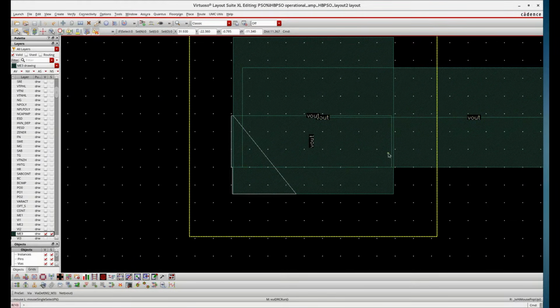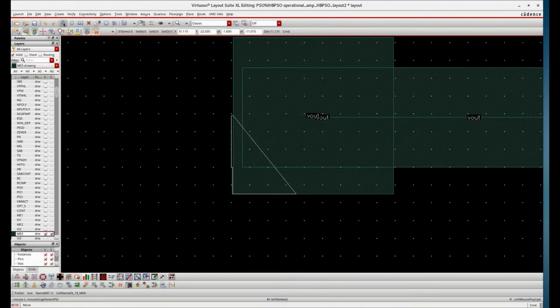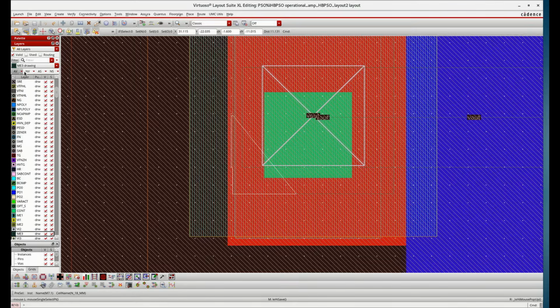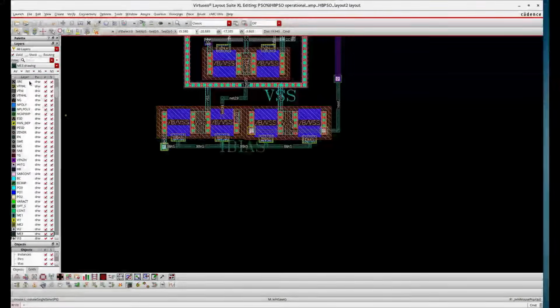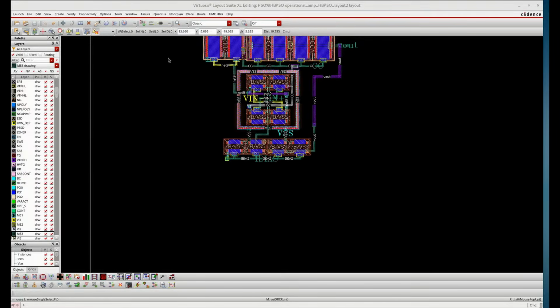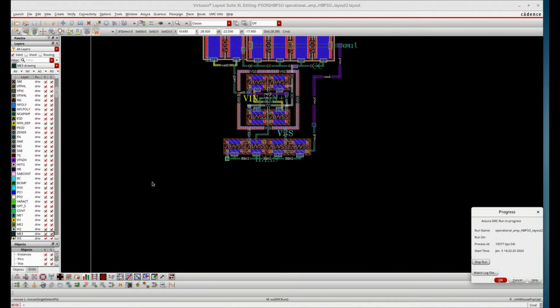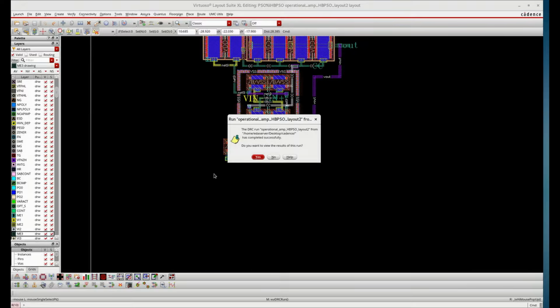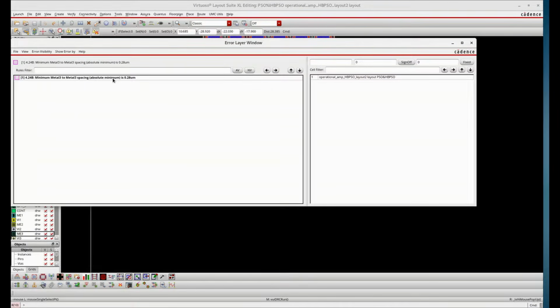So you can individually check the layer. Now save all view. Using the no view, all view switch, you can select the individual layer for better visualization. So let's check the DRC again, whether it is clear or not now. One error is remaining.